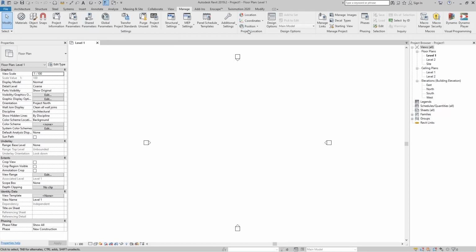In the project location group, we can adjust the exact location where our object is located to get information about the exact shadow position cast by our object at a specific time of day or on a specific date. In the design options group, we can create more options for one of our object designs and present more variants to the investor.